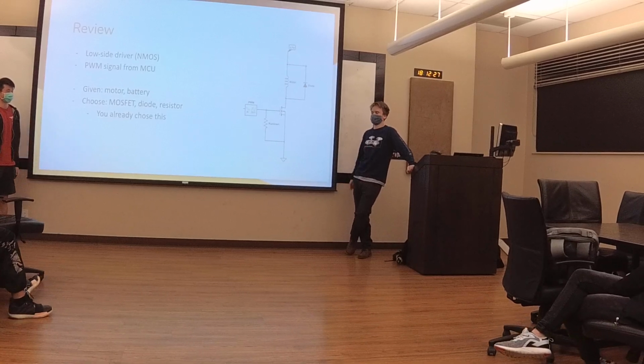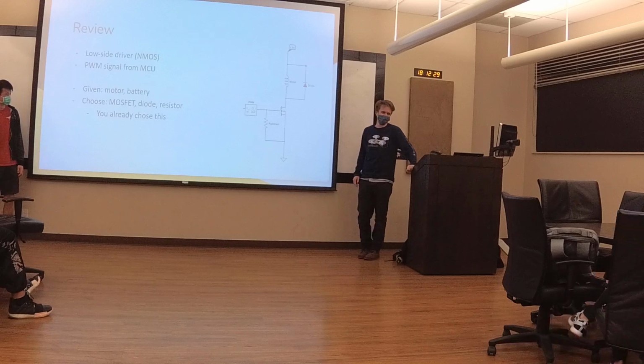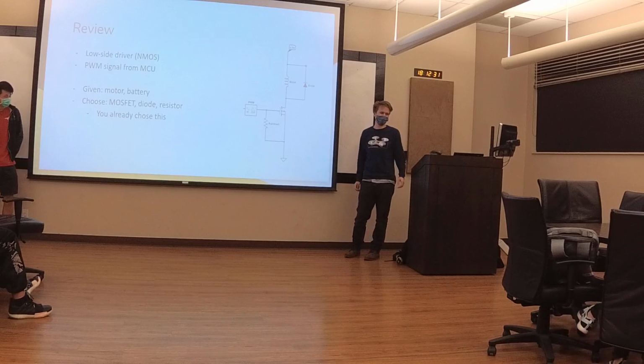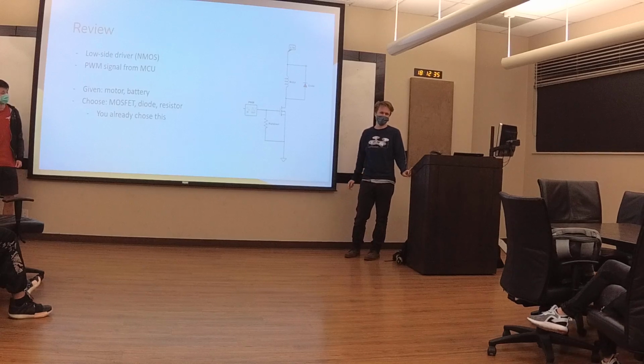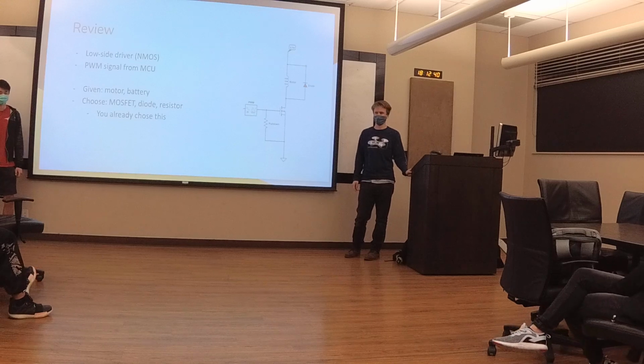So yes, that is true. We do like saving money, and for the same specs, essentially, an NMOS will most likely be cheaper than a PMOS by a couple of cents. But that's not the major reason. Bigger picture. High side requires the use of an NMOS.